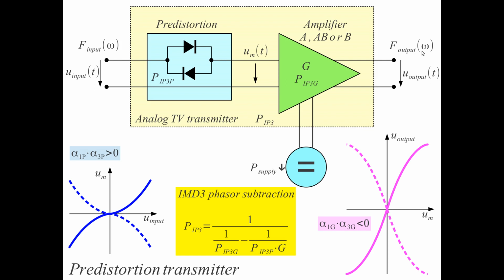But what we are doing today is to have this predistortion done digitally, in the still digital part of the signal, and it's an adaptive predistortion. So the transmitter actually measures its output and adjusts the predistortion to reduce the distortion of the output signal. And this is done today. The adaptive digital predistortion is done in OFDM transmitters. All OFDM transmitters have a digital predistortion, and not a fixed one, but an automatically adapted one. So manual intervention of the operator is not required. So these transmitters become simple.